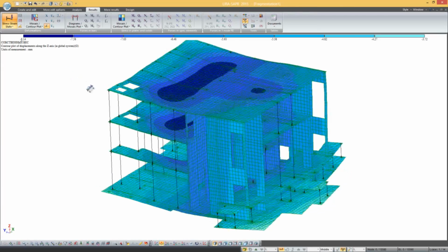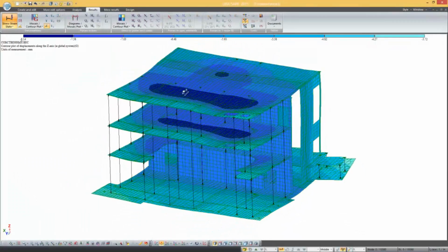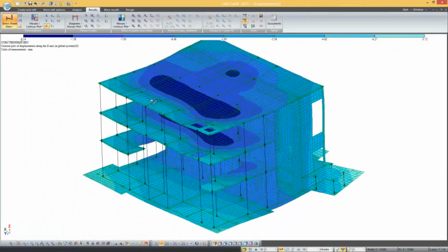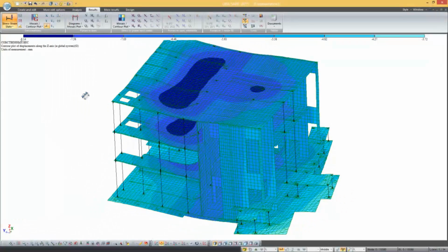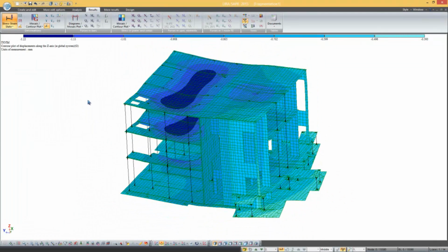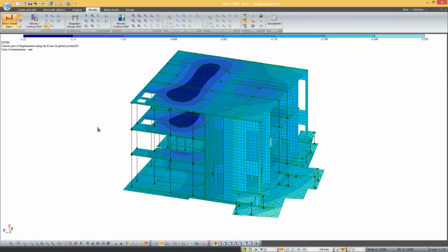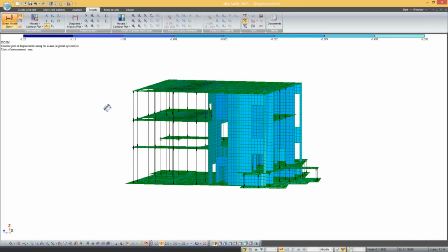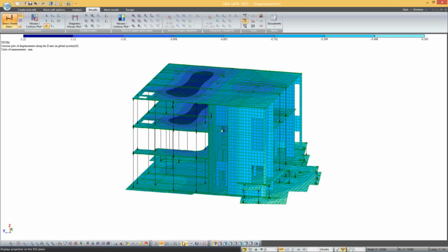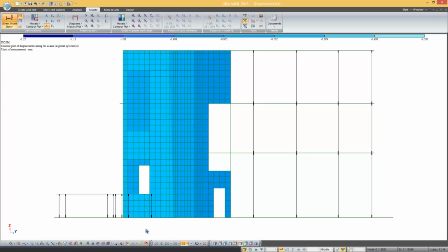Now we see the classic situation when we have a floor slab and we have to consider its deformations and forces in detail. For this purpose, we have to fragment this plate. Let's use the following tools. First of all, it is necessary to disable the display of deformations of our design model. Let's open the vertical projection, where all elements of the slab are clearly visible.